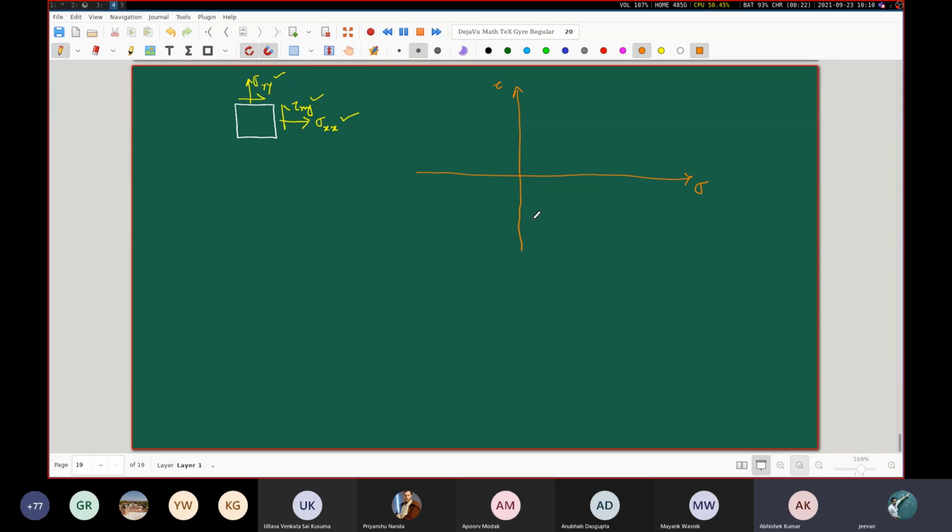It's not like that. There's a certain motivation behind it. So you see here, we want to depict first of all what is available to us. The available information is this sigma xx value, tau xy value, and the sigma yy value. So now on this sigma tau plane, how do we express that? If we can do that, it will give us a method to construct the Mohr circle and to go forward and try to obtain values of the transformed stresses in other planes also.